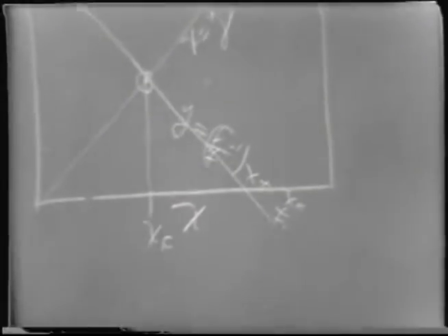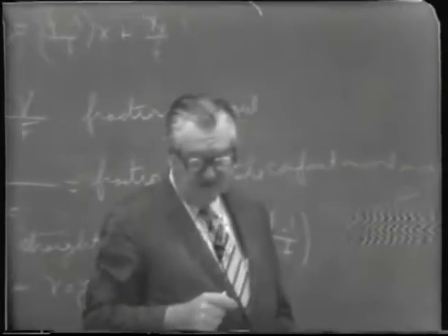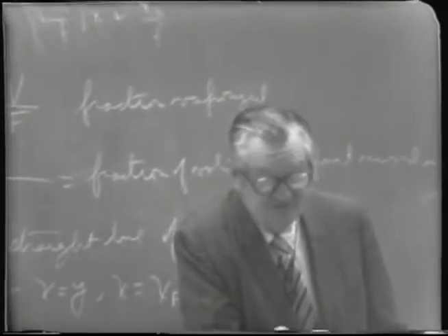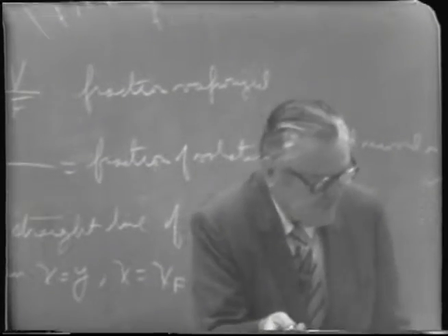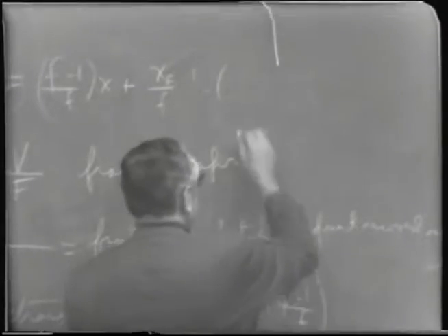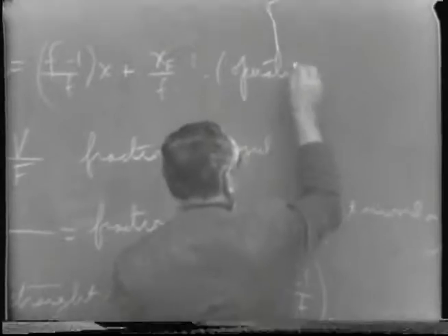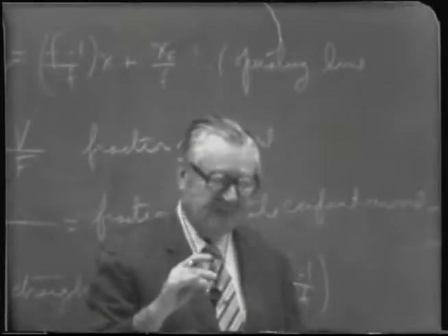Well, note that this equation number 1 is an equation which is determined by what we call the operating conditions. The operating conditions being, in this case, fraction vaporized and concentration in the feed. So consequently, we sometimes call this equation the equation of the operating line, or the line or the relationship determined by the process conditions.